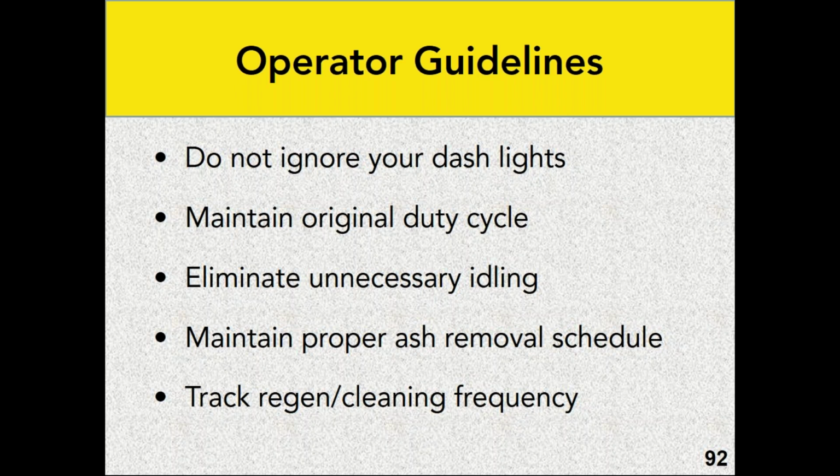And then make sure you properly maintain the ash being removed from these filters. Keep a regular schedule for that to happen. And remember that if you're in dusty environments, you're going to need to do it more often than non-dusty environments. And finally, if you track the regeneration or cleaning frequency, you're going to be one leg up on understanding when the filter actually needs to have maintenance performed.